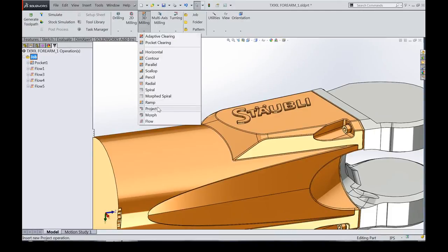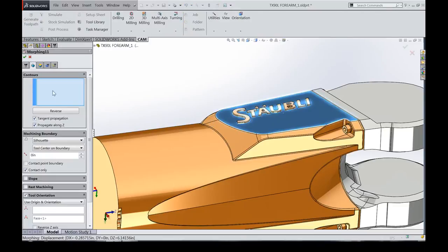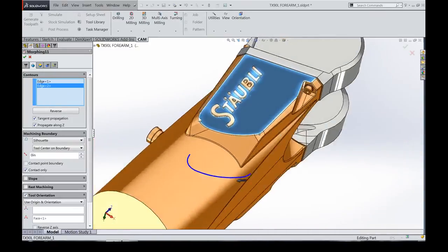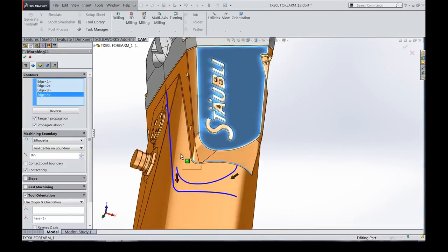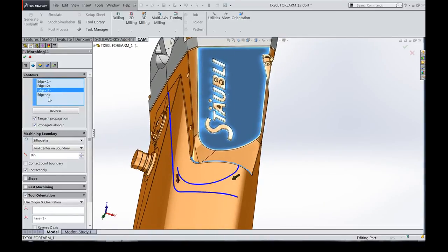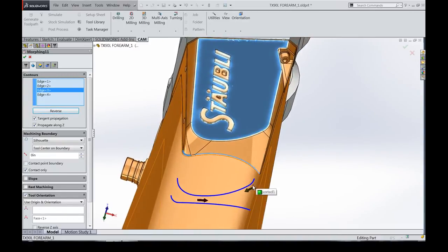I think there's a couple of things that people jump into morph assuming it's just going to do exactly what they want, and they get something that's not what they want. So first, let's make the first newbie mistake here, and that is apparently whatever I did here. I'll just select things wrong. I sort of intentionally did it. If you look at this guide curve, it's heading one direction, the other one's heading the other direction. What's going to happen is it's going to try and morph from this corner to that corner, this corner to that corner, and we'll get something.